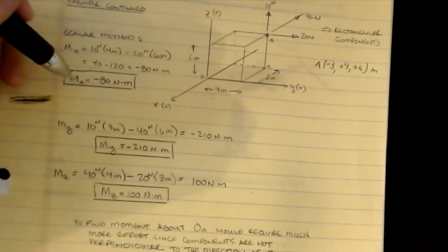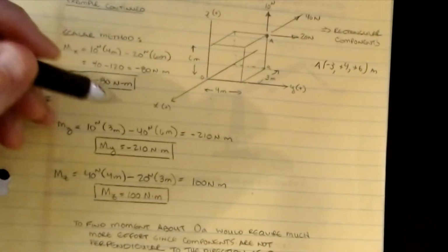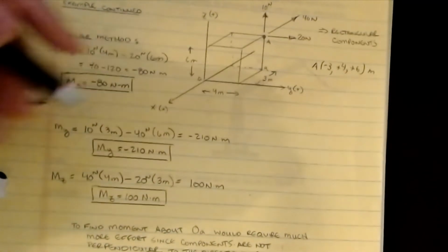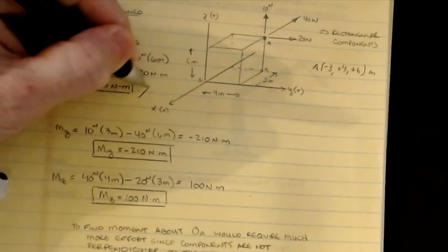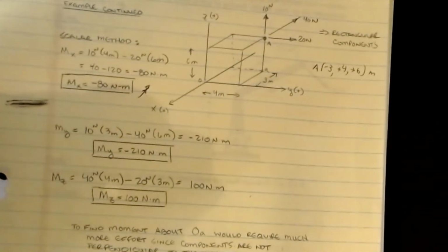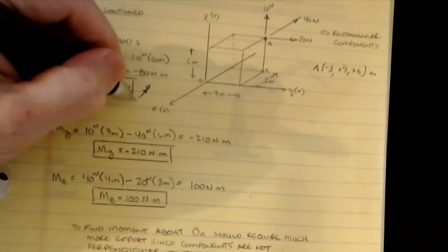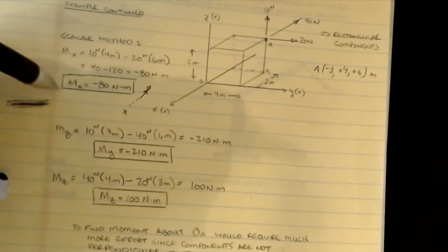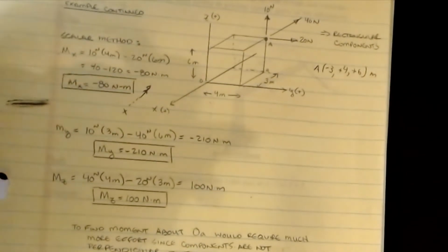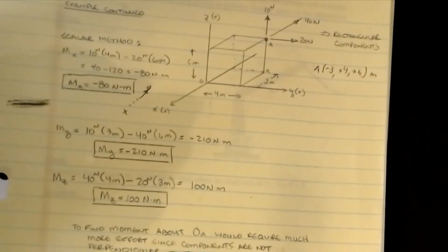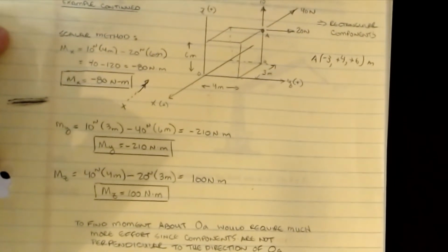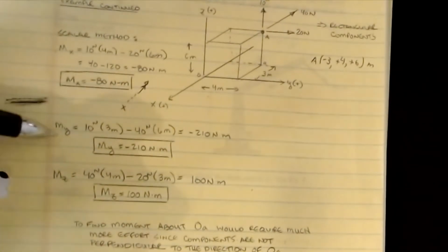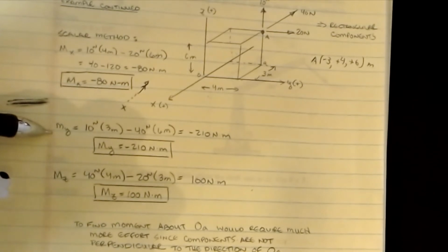All right, so the negative moment tells me that my double-headed arrow would be acting up that way along the x-axis, where this is x. Okay, so that's what that force is doing. And so you see that multiple forces can contribute to the same moment effect depending on their eccentricity. So we have to be very, very careful in what we're trying to do. Okay, now the My moments: let's see if we can figure out which forces go with them.